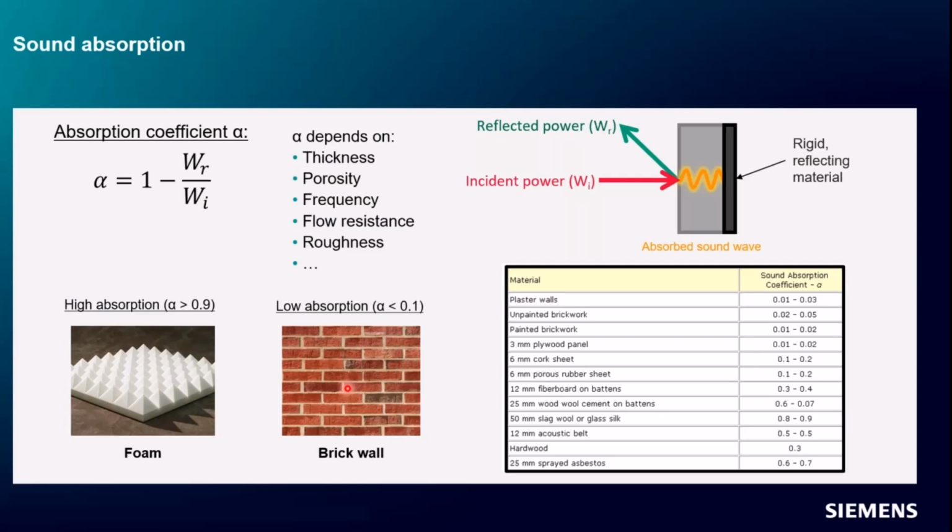Okay, so different materials have different alpha values, and these are some very generic values you're seeing. Obviously a 6mm porous rubber sheet could be a number of different varieties. We're saying in general it's not a very good absorber, and we're also giving you an averaged value over the frequency range. As we'll see, alpha and sound transmission loss are quantities we measure versus frequency. It's not the same per frequency band. So giving it one number is really averaging upon an average, and it's just a generic number that isn't incredibly useful for engineering purposes.